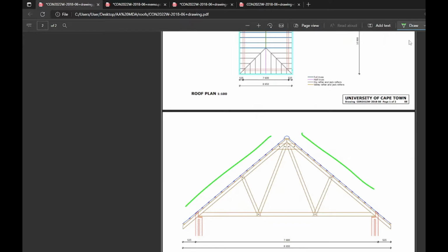So let's go down here. You see in this drawing, actually, the wall plate's been indicated. And the only thing holding these trusses down, other than their own self-weight, their own dead weight, is the hoop iron that we're going to add now. I'm not exactly sure, but one end goes in that side. I think it might go over both the tie beam and the rafter, and I don't know how many times I loop it, but it's long, 1.5 meters long.